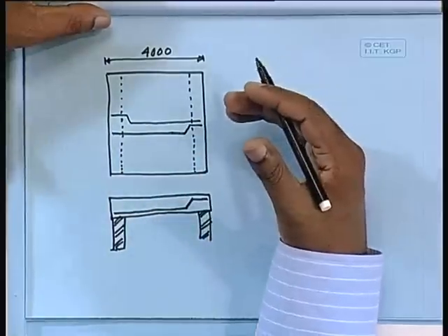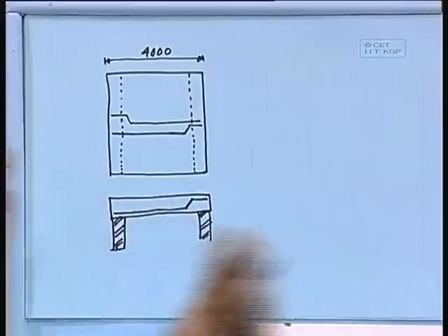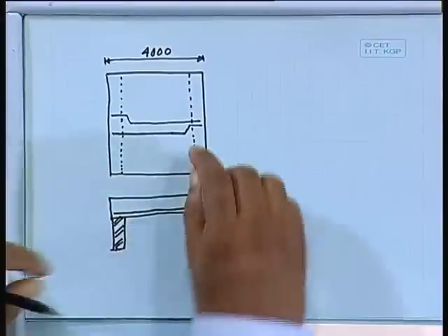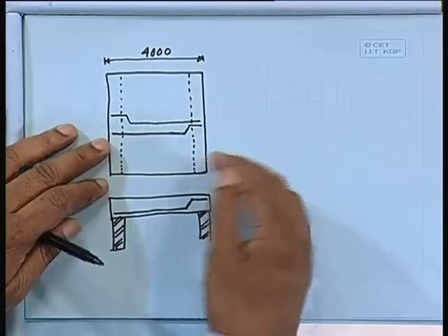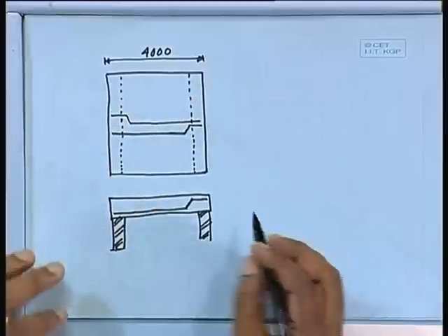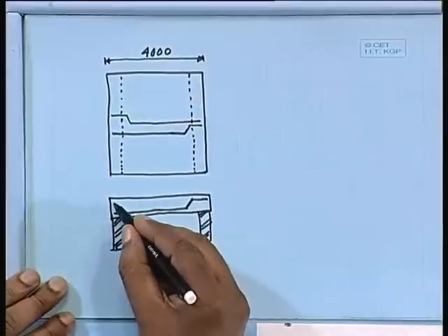So, your reinforcement will be same, the bars will be same, only thing one will be placed this side, another one will be placed other side. It will be cranked on one side only, at the construction site they will crank on one side, but they will place alternately. So, I shall get the other reinforcement like this.